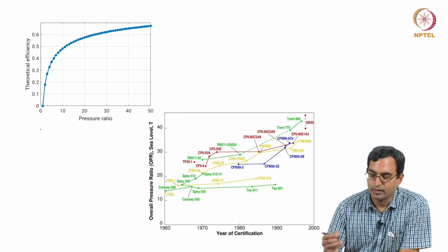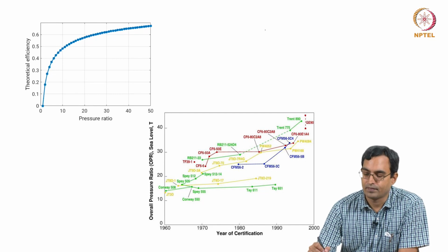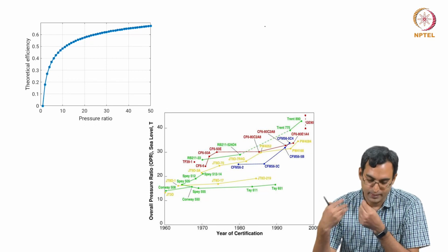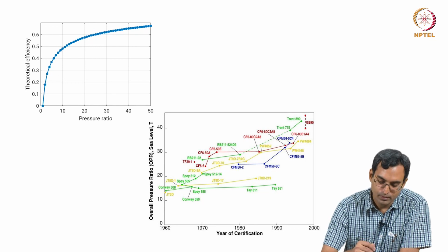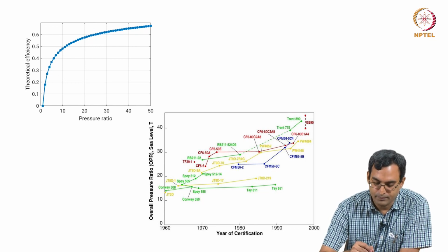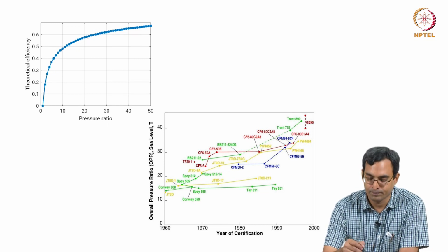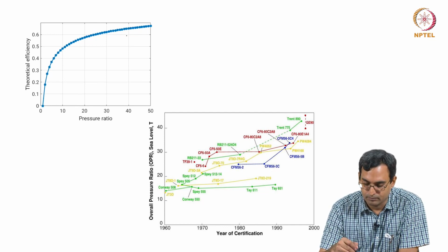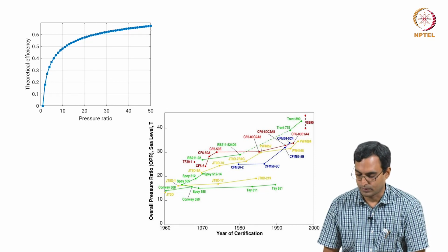So, we already saw in the case of a Carnot cycle that the efficiency cannot be 100%. The efficiency depends on the ratios of the temperatures at which you reject and have heat added. In a similar way, in this cycle it depends on the pressures. So, you see that if you have a pressure ratio of about 10, the theoretical maximum efficiency you can have is less than about 50%. As you go to a pressure ratio of say 45 or so, we are somewhere around 65%. As we go to beyond 50, we get close to around 70% or so.